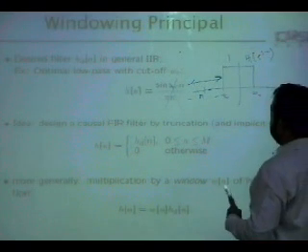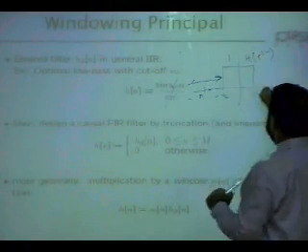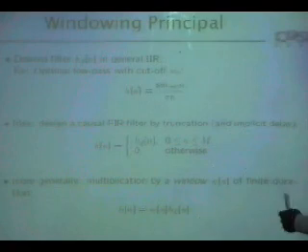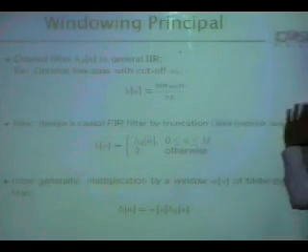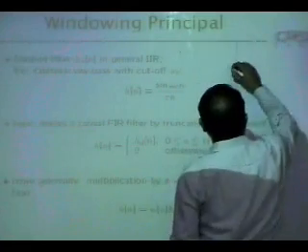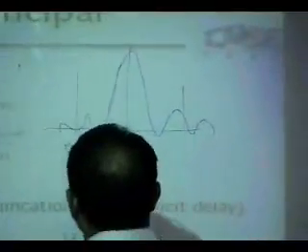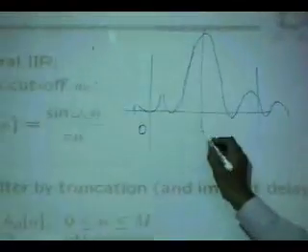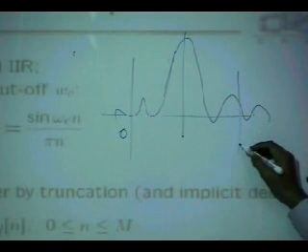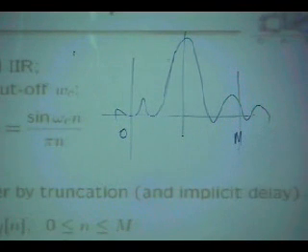So that really says, if you really want to use it, the only way of using it is to shift it to make it causal and cut it. Okay, so you say, shift the sinc and cut it. Start from 0, and the center should be in the center. So you say, okay, from 0 to M coefficients. But you have to make it causal.